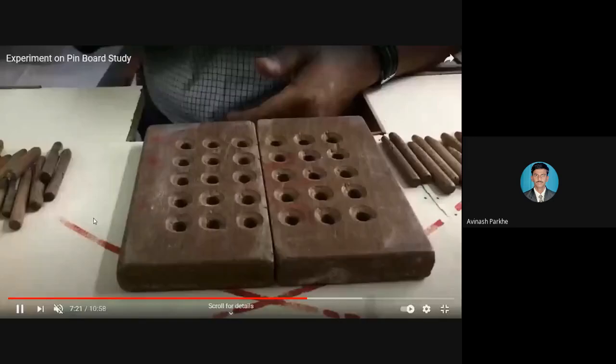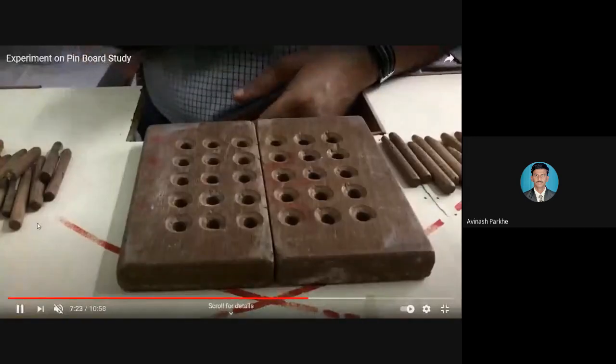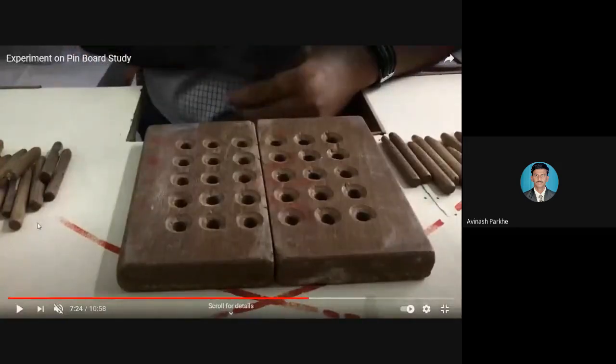You can see in this particular one, this is called bevel holes. So what is the difference from the holes in the previous board? The straight holes are there. Such types of sharp edges are not present at the top side. If such sharp edges are not available, sometimes the pin is not properly inserted in the hole. So if the straight hole is available, we are facing some problem.